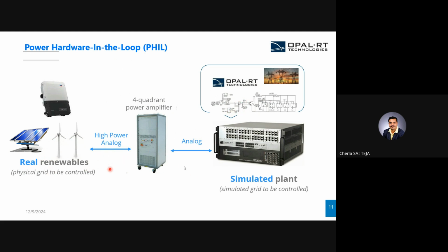We can test in a safer environment, then proceed to commissioning this real controller into the real PV farm. Nowadays, these power hardware in loop tests are picking up pace, and most research institutes, both in academia and industry, are going forward to test their control algorithms in this PHIL environment as a validation step before going into physical testing. So this is about power hardware in the loop simulation.